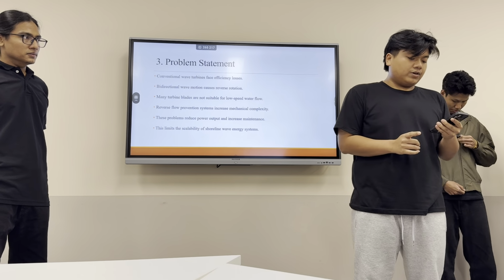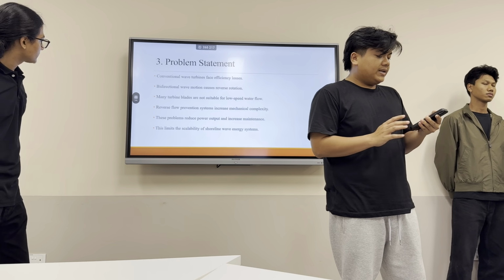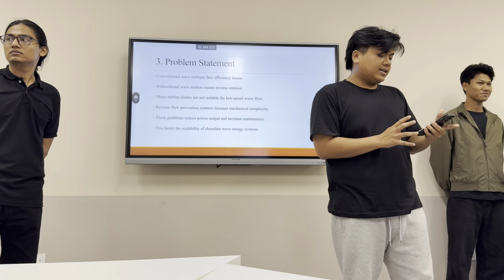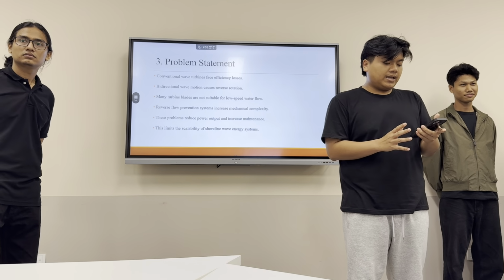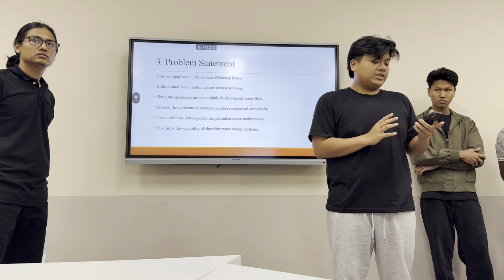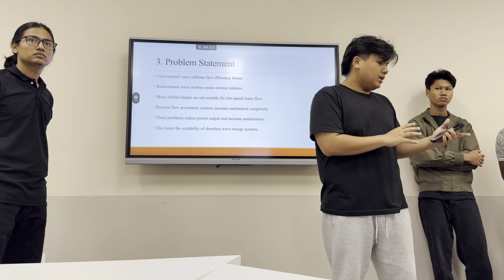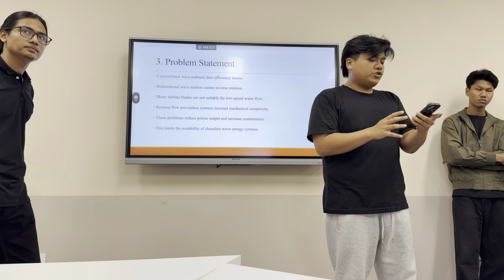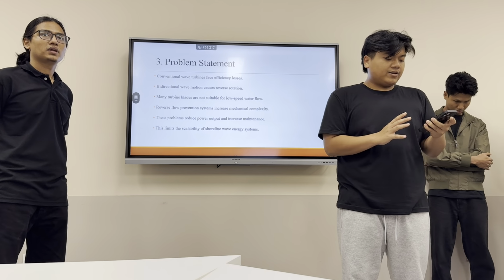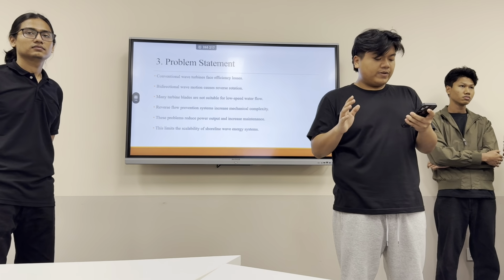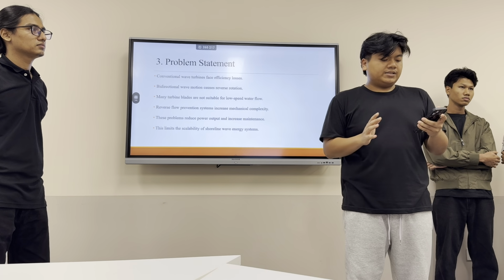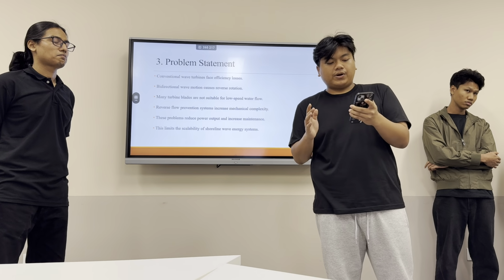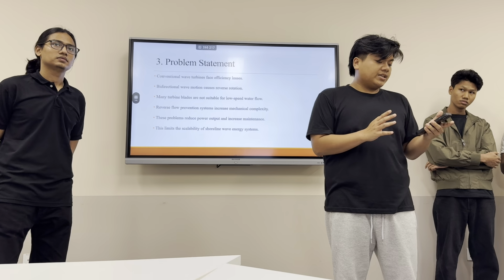Another major issue involves the geometry of the turbine blade. Many existing shoreline turbines use straight or simple blade designs, usually adopted from other turbine systems and not optimized for the relatively low water velocity near the shoreline. Since shoreline waves often move slower than offshore currents, the turbine blades cannot capture enough kinetic energy from the moving water. As a result, the system produces lower torque, meaning the turbine cannot rotate strongly enough to generate significant electrical power.